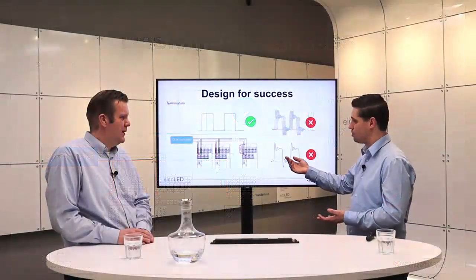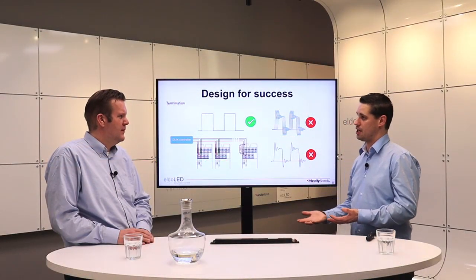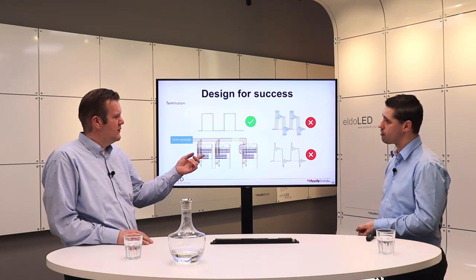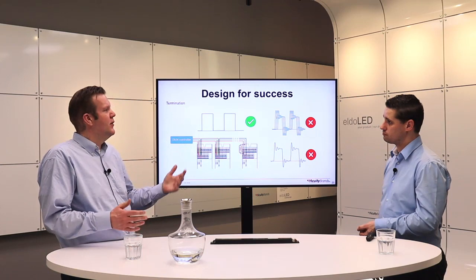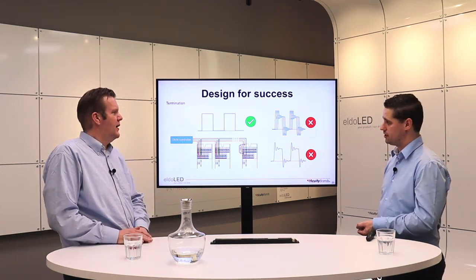But at a certain moment in time, you get so much noise on the line that the luminaire is not capable of receiving that signal in the correct way. Got it. And that decoding is done in the so-called transceiver module of the driver. Indeed. Okay.